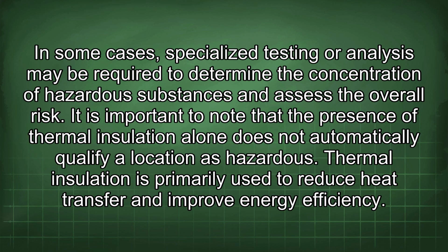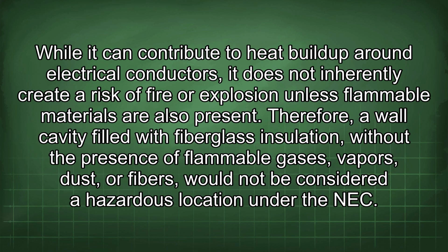It is important to note that the presence of thermal insulation alone does not automatically qualify a location as hazardous. Thermal insulation is primarily used to reduce heat transfer and improve energy efficiency. While it can contribute to heat buildup around electrical conductors, it does not inherently create a risk of fire or explosion unless flammable materials are also present. Therefore, a wall cavity filled with fiberglass insulation without the presence of flammable gases, vapors, dust, or fibers would not be considered a hazardous location under the NEC.